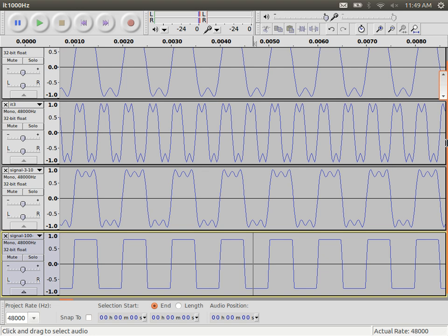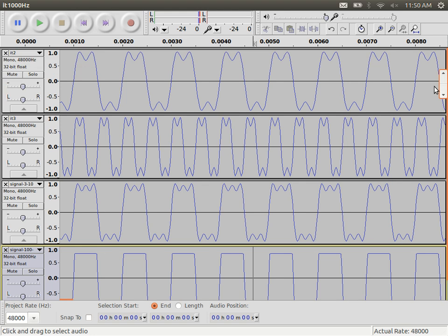That is, in the top signal, it's possible if we transmit the top signal that because of some interference, what's received is that it goes low and then it goes low again because of interference. And the receiver would interpret that as 2 low signals, low, low, low. So the more accurate or the closer we are to this digital square waveform, when we transmit, the less chance of errors in the transmission.